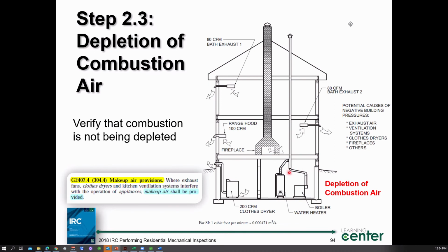I haven't even mentioned category 4 appliances. You know, we see category 4 appliances, ladies and gentlemen, often. These are our high efficiency appliances. You know, we're allowed to vent these things with plastic pipe. They're sealed combustion chambers, right? Where I can bring all combustion air from the outside through a pipe into the appliance and then take a plastic pipe out as the exhaust, and I don't have any need to bring in combustion air at all from the outside. Those appliances are really nice.